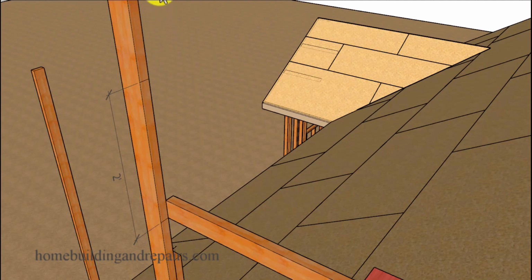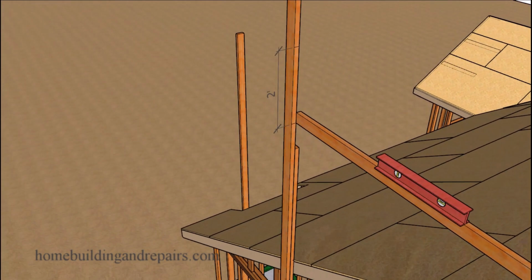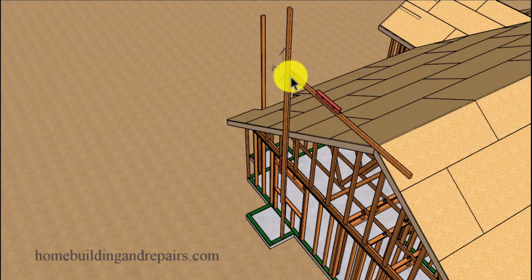And that's what I did when building the 2 chimneys. Instead of going with 24 inches, I made this measurement 30 inches. So 30 inches from this point here to the top of the chimney wall framing studs. And this measurement will work for all of the framing studs as long as you're dealing with a level concrete pad or a level foundation.